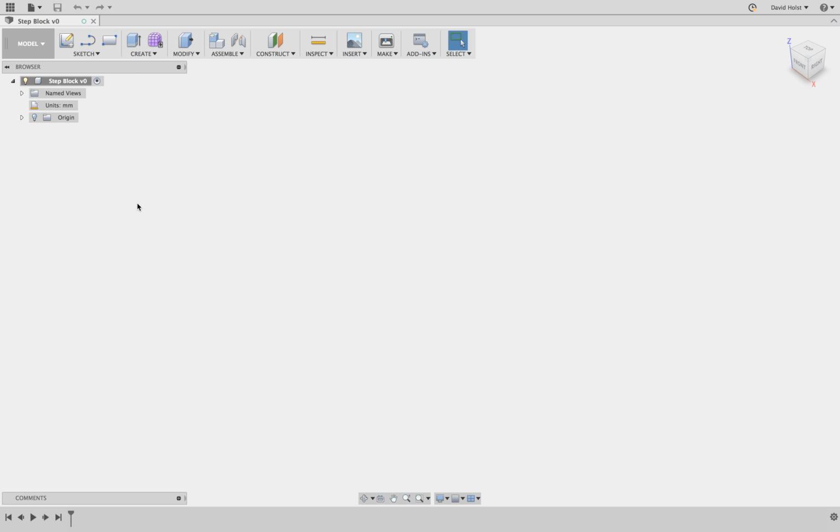So in Fusion 360, usually you do a 2D drawing and then a 3D operation to it. That's how you get started. So the very first thing we're going to do is we're going to create a sketch. So if this button here, the create a sketch button with the picture of the pencil, we can click on that one. And then what that's going to do is that's going to allow us to start sketching on a surface. Okay, and it's given us these 3 options here.